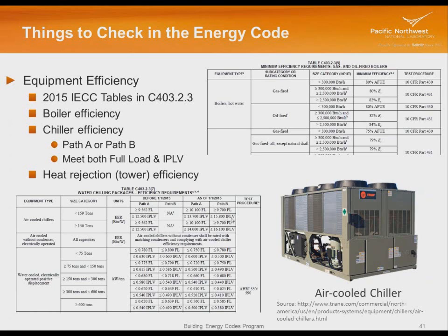And there's a benefit to having a part load efficiency that's higher and not such a great efficiency at the peak load. Remember that diagram we had in the economizer. There aren't that many hours of cooling at peak load. Most of our hours of cooling occur at part load, so we care about that efficiency. So full load is marked FL, IPLV is integrated part load.